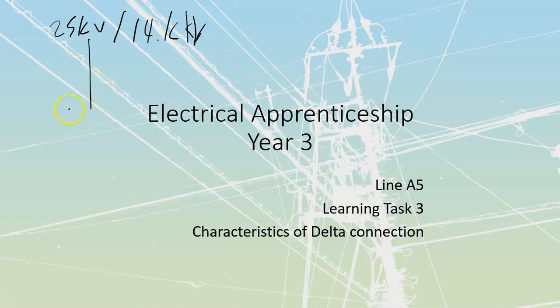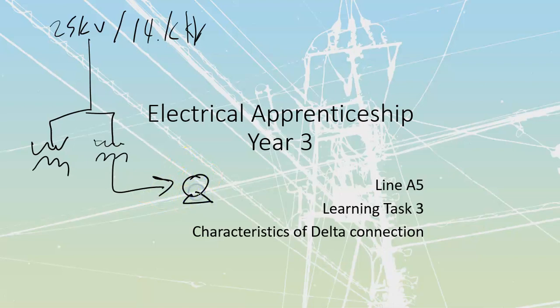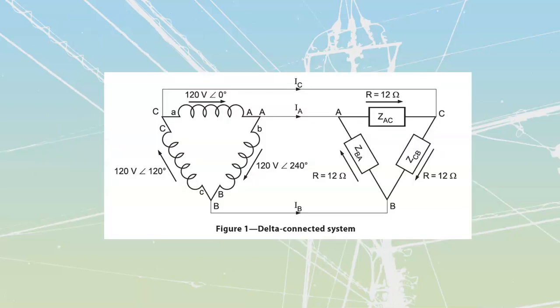They come in from there and then distribute out through a pile of transformers. We'll draw them here as a one-line diagram to a bunch of the other areas inside their plants. Some of these areas are motor loads alone. Those motor loads work particularly well off of a delta service because a 3-phase motor doesn't need neutrals. So they're more common in this type of application as part of a subservice, not as the actual BC Hydro service, unless you're dealing with an older installation.